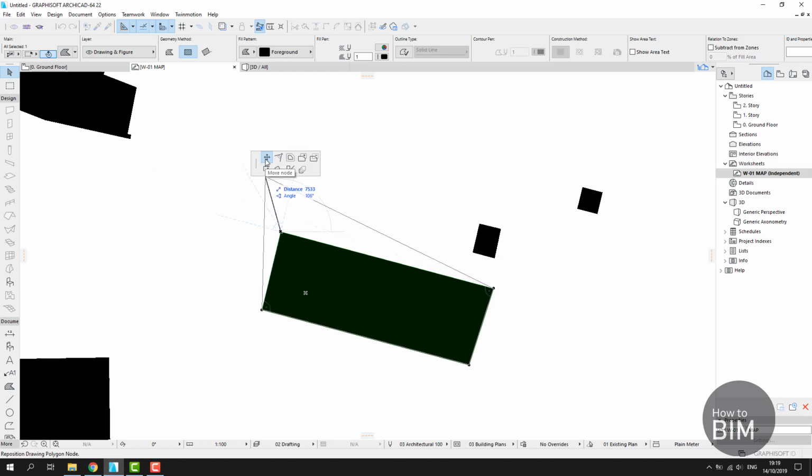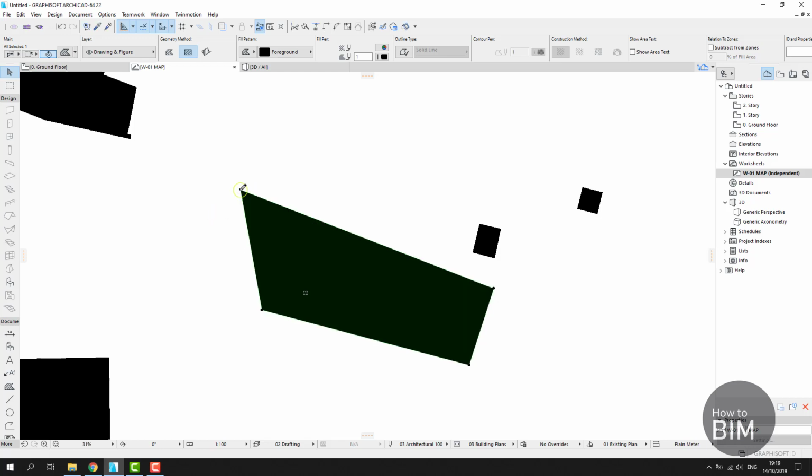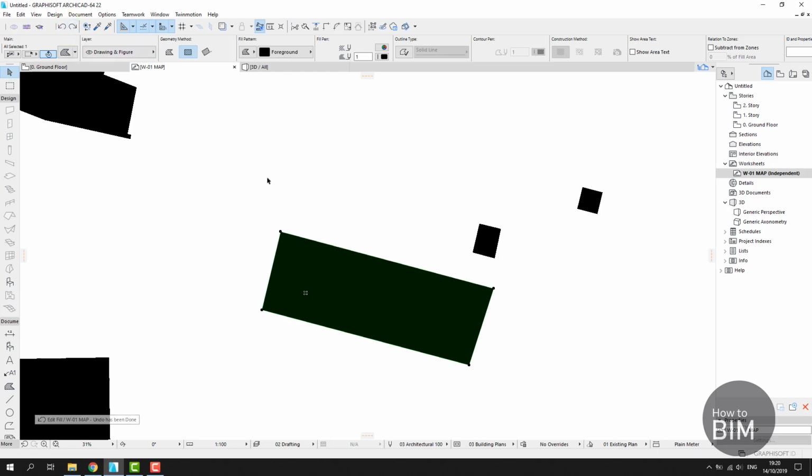The first and already selected tool is Move Node, and from the visuals you can already see that I'm actually moving this corner point, and if I click left again, it's done. The change is permanent, or permanent so far. I can undo by clicking in here, or by Ctrl Z, as in any kind of Microsoft related application.